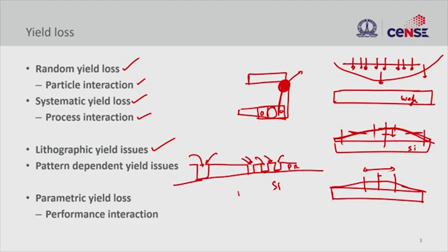So the etch rate between these two structures is going to be different, and this is again pattern density dependent. This will also affect your CMP and fill and everything as well. So pattern density is something very important.